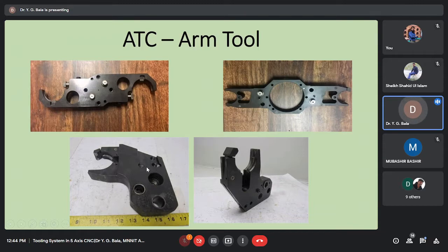Okay, so here once it has to pick from the spindle, it has to load it in the chain, and then pick from the magazine, and then go to the spindle to locate. So the number of degrees of freedom, that is rotation, will be more for this single hand. That means the timing for changing your tools will be more.